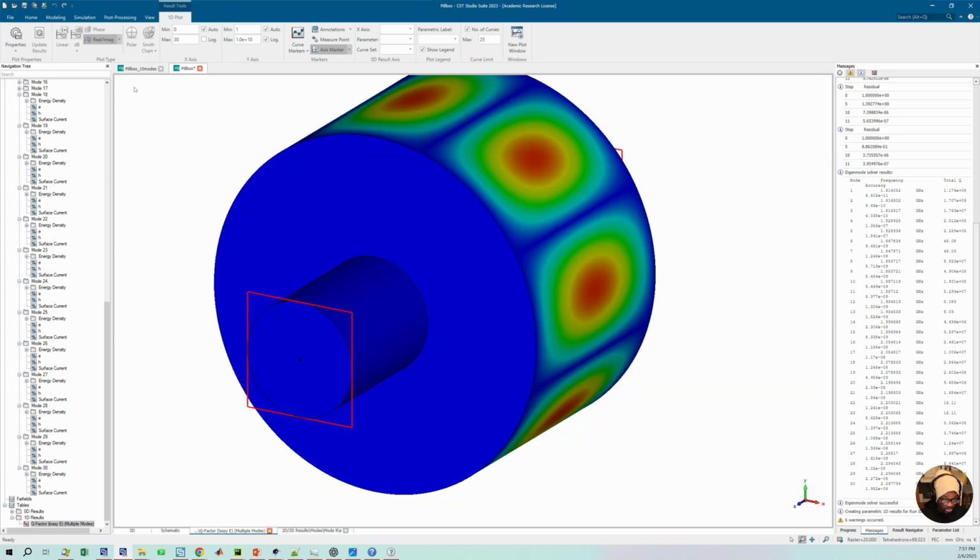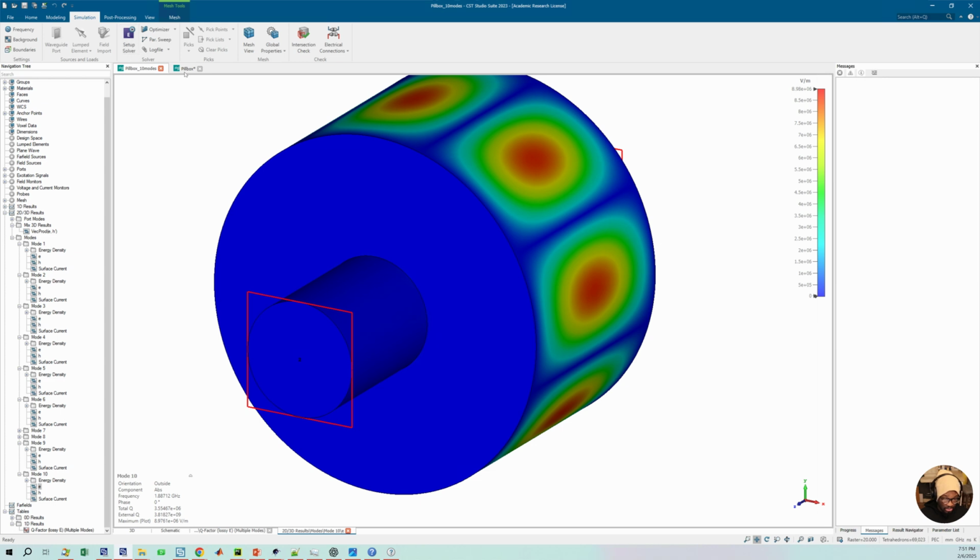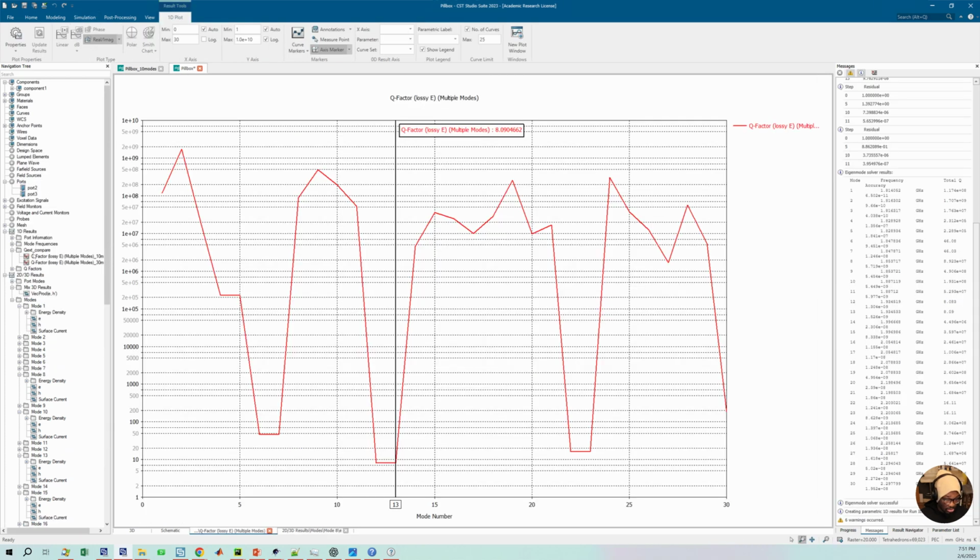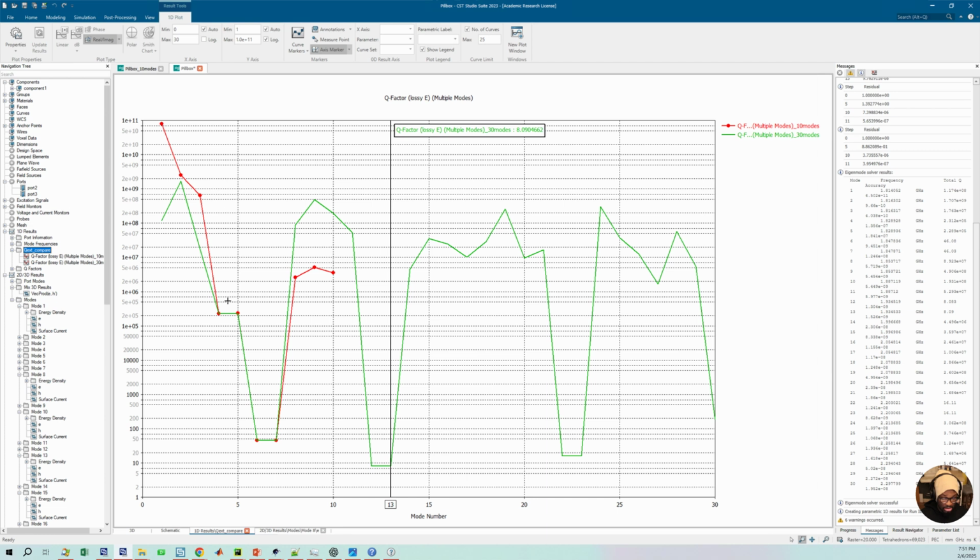Now what I did was I took the result from this and compared it with this, and you could see for yourself that for the modes that are propagating, the external quality factors align, which is only these modes, mode 13 and these other ones. For these low Q modes, I also checked mode 23 and mode 30, and they corresponded with the result. But for the other ones, where the Q is high, you see that the results from the two simulations do not correspond.